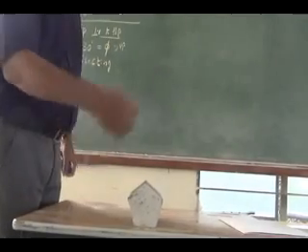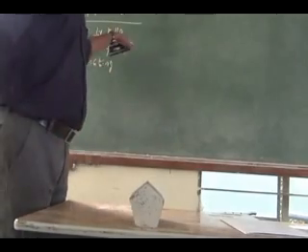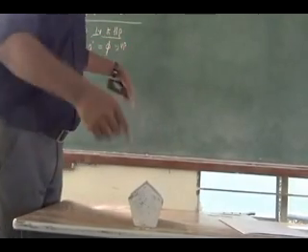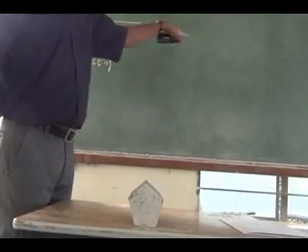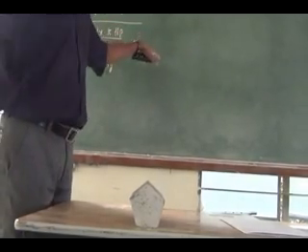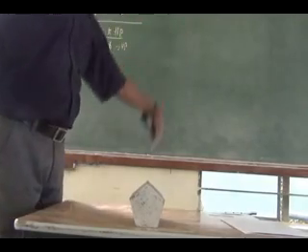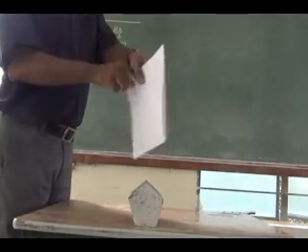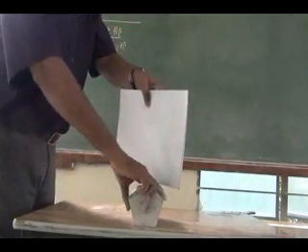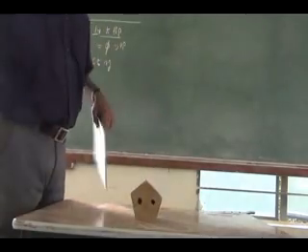Where will I have my base? It is on VP. Since the axis is perpendicular, how do I have to draw it? The pentagonal base, true shape, will be resting with one of its sides on the reference line. Then you project the top view. Listen here, once I have cut the solid using my cutting plane, I will be removing one part.